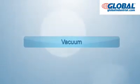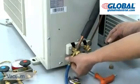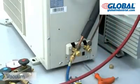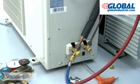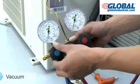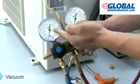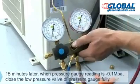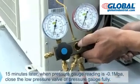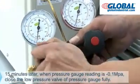Vacuum. Connection of vacuum pump. One end of the filler wire of pressure gauge should be connected to the vent of vacuum pump. The other end is connected to filler mouth of low pressure valve. Open low pressure valve of pressure gauge. Keep high pressure valve closed normally. 15 minutes later, when pressure gauge reading is negative 0.1 MPa, close the low pressure valve of pressure gauge fully.